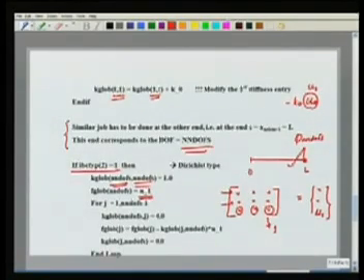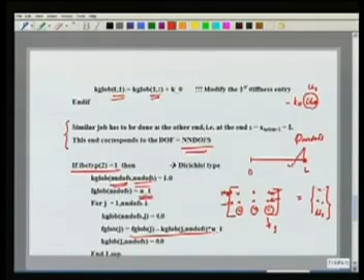These entries have to be suitably modified, that is the global vector for all other rows, that is all the rows above, will be modified by the entries in the last column. So last row and last column. So what I am going to do, f glob j is equal to f glob j minus the stiffness entry corresponding to the last column. I am going to take that stiffness entry multiplied by the known displacement value at this end, and simply subtract it from the load vector corresponding to that row, and then I will set that corresponding stiffness entry to 0.